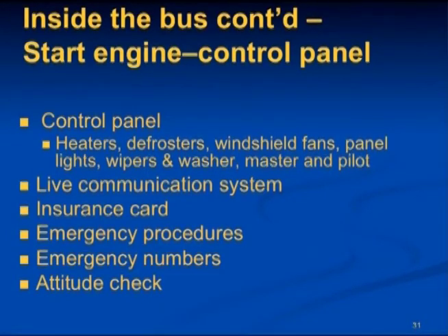And don't forget your dash lights. You need to be able to read all your gauges, the speedometer, and the tachometer. The lights should be in good condition. Record any malfunction on your pre-trip form and have it repaired.